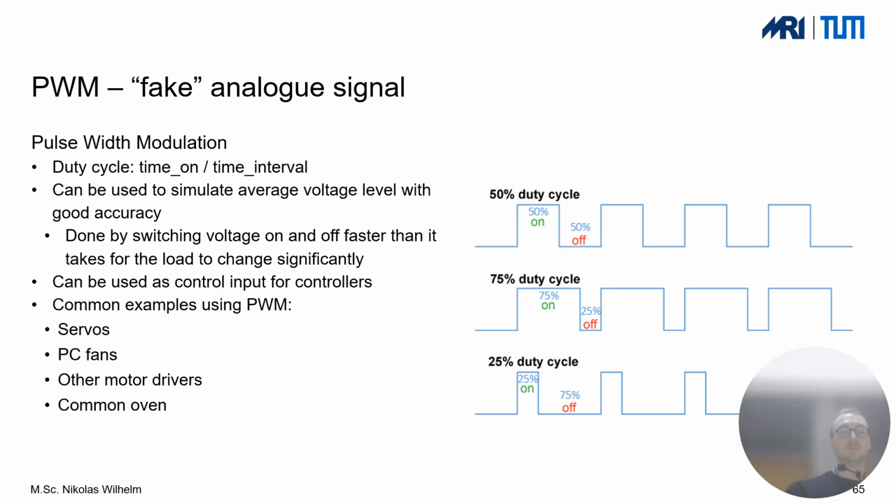A very pragmatic solution for communicating, for example, with our motors or displaying some status from an LED is to use PWM. It's called pulse width modulation, and the idea is quite simple. You simply define a duty cycle, which is the whole time of that respective cycle, and then you set your PWM signal to be active for a certain amount of time within that cycle.